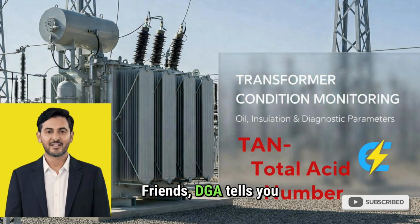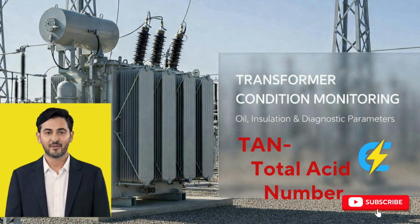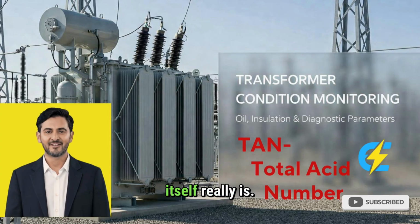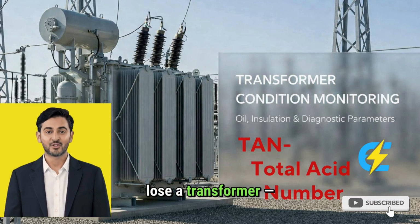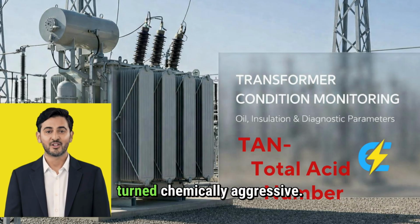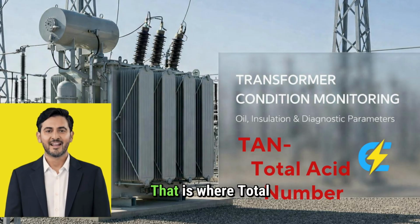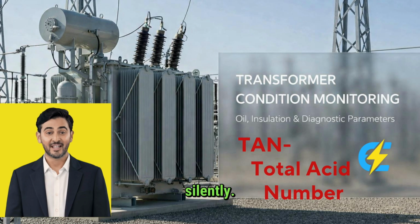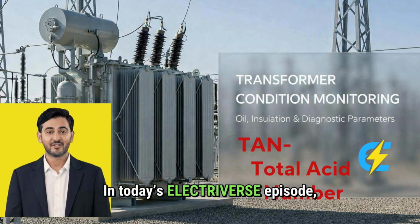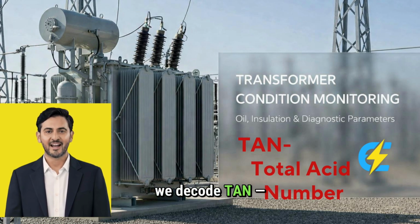Friends, DGA tells you what is happening inside the transformer, but TAN tells you how healthy the oil itself really is. You can have perfect gas values, no overheating, no arcing, and still lose a transformer because the oil has turned chemically aggressive. That is where total acid number comes in. When TAN increases, oil stops being an insulator, starts attacking paper, corrodes metals, and accelerates aging silently. In today's Electroverse episode, we decode TAN, total acid number.